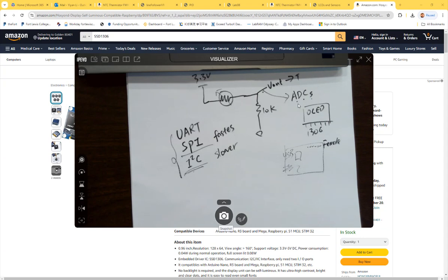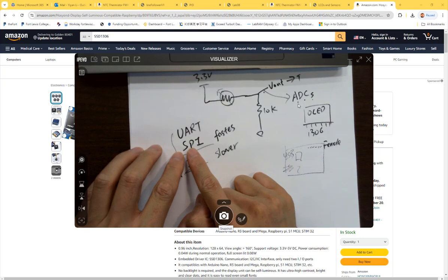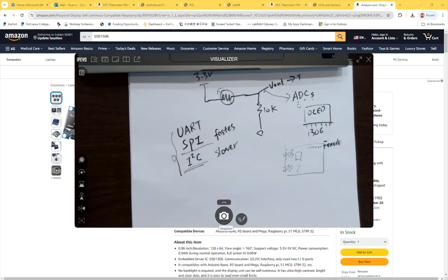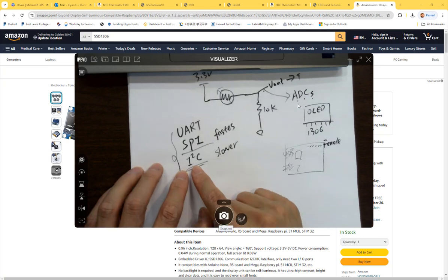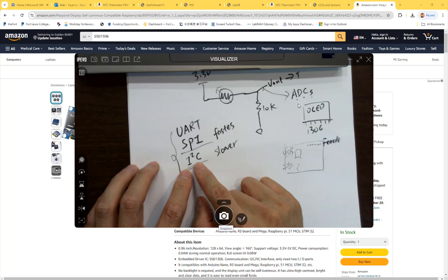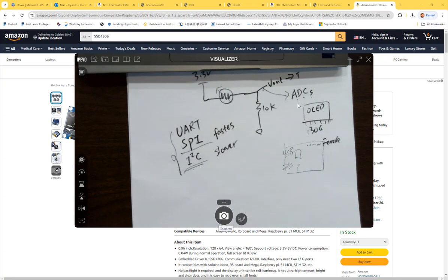If you want to apply an SD card module onto your PCB or in your project, you can start working on that Lab 9 a little bit now. Since you usually have megabytes, hundreds of megabytes or even gigabytes of data to be transmitted, usually we use SPI for SD card communication. For I2C, it's slower, but it's better for long distance transmission.